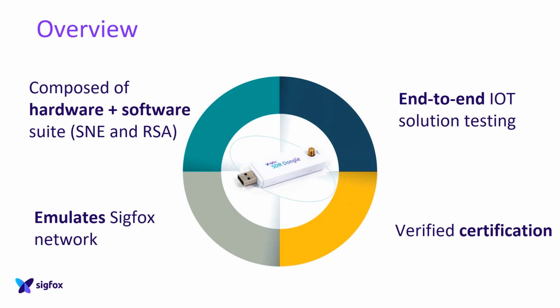It basically emulates a Sigfox base station, to retrieve the radio signal of devices, and it also emulates features of the Sigfox cloud. So you can configure callbacks as well to send your data to your application servers. And by doing that, you can do some full end-to-end IoT testing using the SDR dongle.